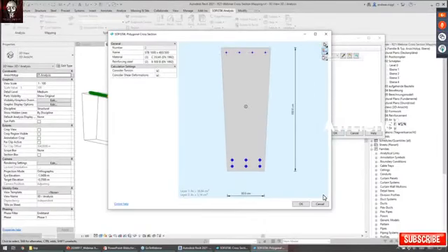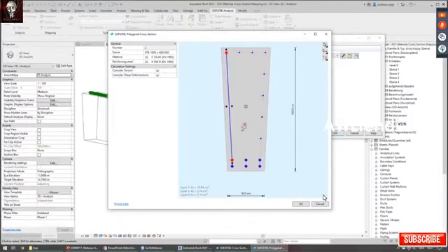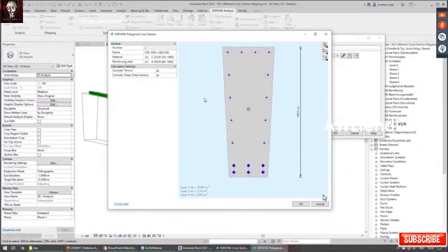And finally, I add another layer of line reinforcement at the sides, for example, to account for torsional stiffness here. I reduce that to smaller bars, and I also deactivate the outer bars of this layer because there are already 2 bars present. Maybe assign them to a different layer number. Same for the other side. You see the grip points. And now you see I configured this section, manually configured the rebars in this section.